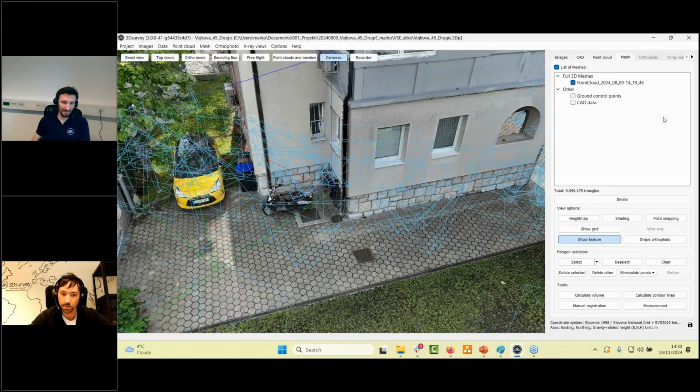This can be done. The most important part is to have some ground control points, tie points, to align those two models together. If you have those, or even if you don't, you have to make sure that the two models cover at least 3 points that are easily recognizable on both of them, and then you can combine them together in a 3D survey. We have made this possible with the Transform tool or the scan module.